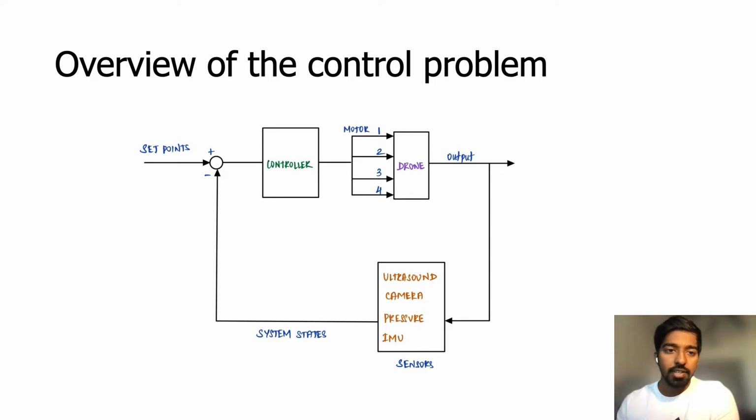The system states include angular position, altitude, and horizontal velocity. And the software runs an algorithm that takes in our set point and estimated state to calculate the precise motor commands that will inject the necessary force and torques into the motors. That forms the controller.